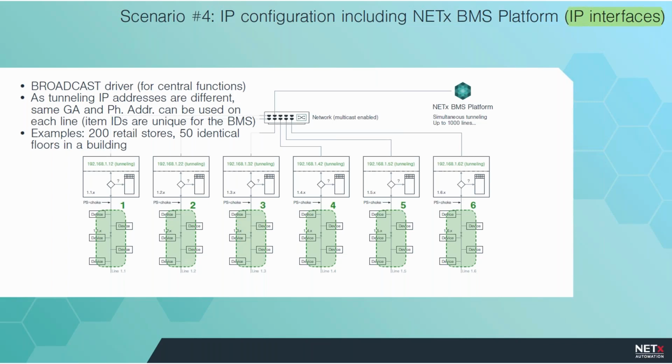An IP router is giving us both connections, not only the tunneling connection that is in principle used only for configuring, for example, connecting to a specific part of the installation through a tunneling using a specific IP of the gateway, to configuration, for example, for the ETS commissioning or whatever. And the other connection is the routing multicast that is used for the communication to send the different telegrams between the lines, is the coupler functionality.